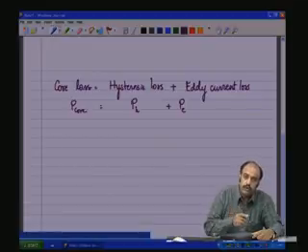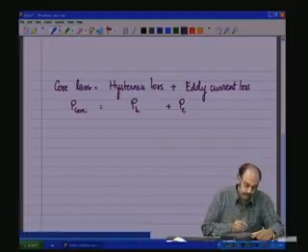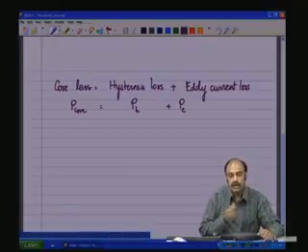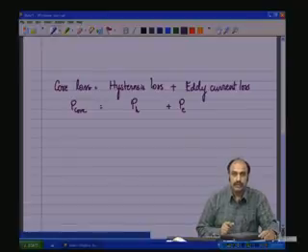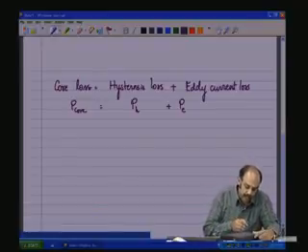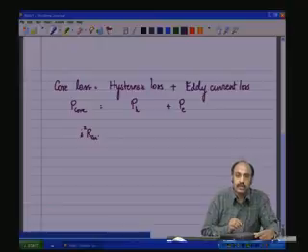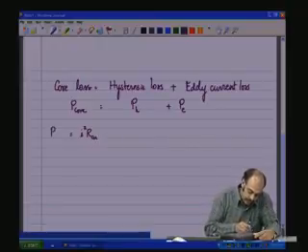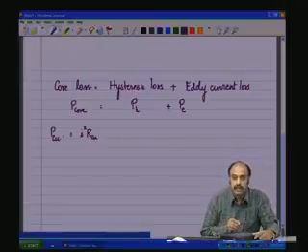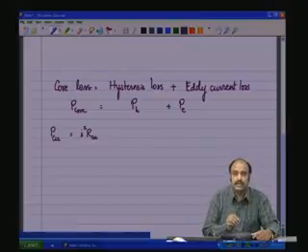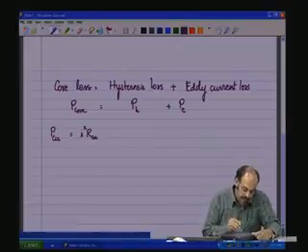And as currents are flowing through the copper coil, there is going to be some finite resistance associated with the copper coil which is wound on the transformer core, the primary and the secondary, and there is going to be an I square R loss associated, and that is called the copper loss, due to the fact that there is current flowing through it and a finite resistance associated with the coil.